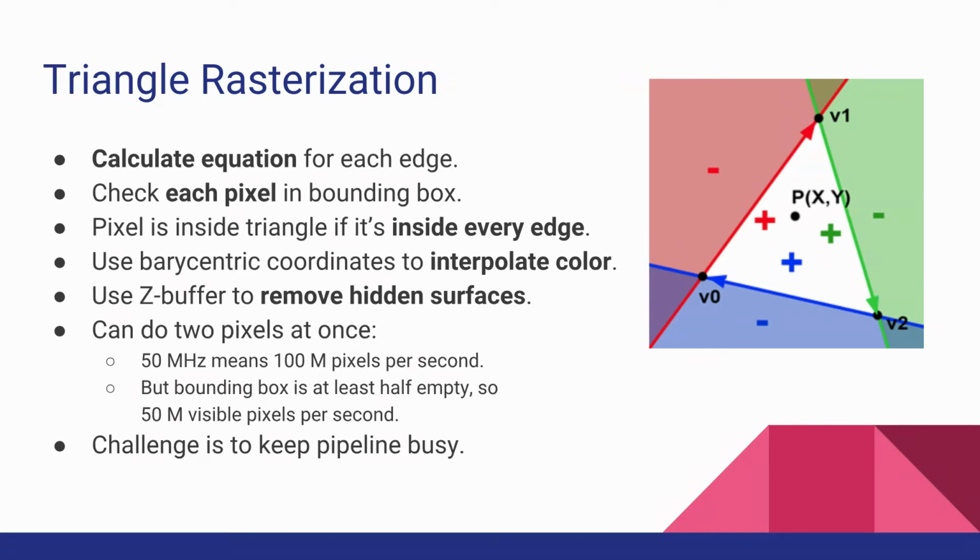In the good old days of static RAM, you put an address on the bus, and it said read, and then on the next clock you had your answer. Now it's super complicated, where these RAM chips are really complicated. You have to go into a special mode, pass it a command and give it an address. Then it can take dozens of clock cycles before you get it, or it can take 1 clock cycle. That variability is a real problem all the time, because if you don't do it well, then a lot of those 50 megahertz, you're just stalling on RAM.